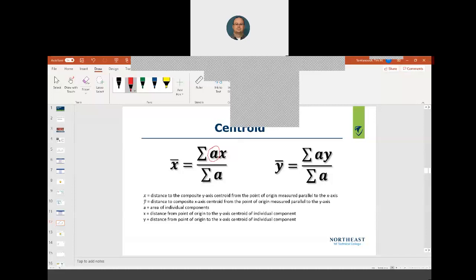If our load does not go on the centroid, we will create a moment. And we all know what a moment is: a force times a perpendicular distance. This is why it's important in design that we know where this is. Basically everything is exactly the same, because we are assuming the material is homogeneous and of uniform thickness, which is typically true in building materials.